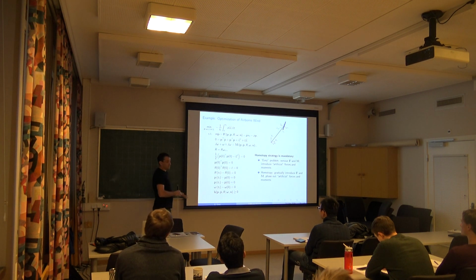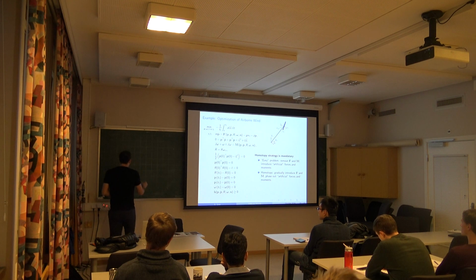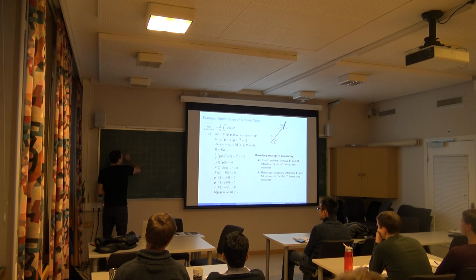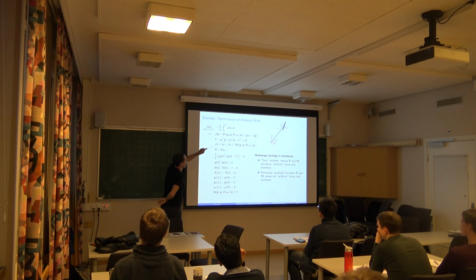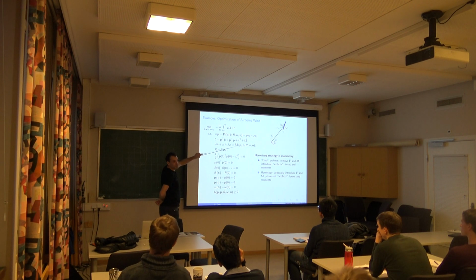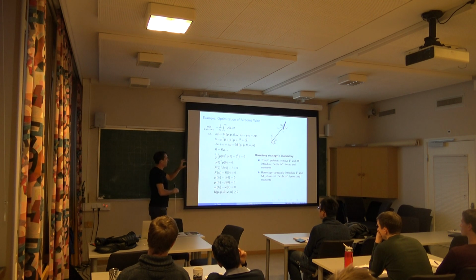We have to use homotopy strategies in this context. If you just throw the problem in there, it will never work. So what we start is by asking the solver to, for example, fly a trajectory, find something feasible, maybe like just a tracking problem. So we start the NLP with an objective function that is fly this circle. And we also start the problem with introducing our own forces and moments in the model. So we basically control completely the flying machine here. And we solve that first.